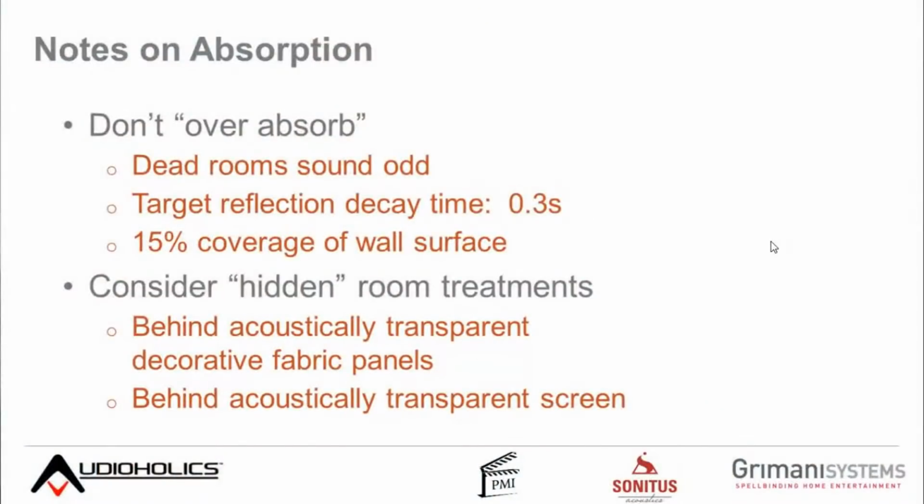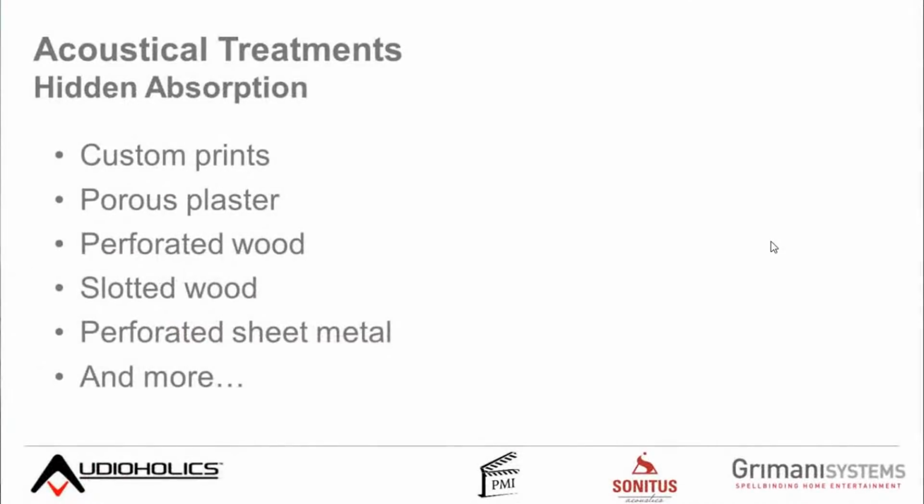That's ridiculous. Okay, so you can also put treatments behind an acoustically transparent screen if you're using that for your video. That's another place to put them. Other ways to conceal these things, other than a stretch fabric wall, which is a common thing to do, and much later in this presentation I'll show you a bunch of pictures of that. It doesn't have to look like a typical upholstered room with all this decorative stuff. It can actually look like it's just been painted, or like it has just wallpaper.